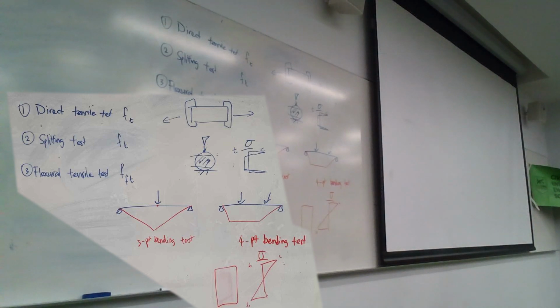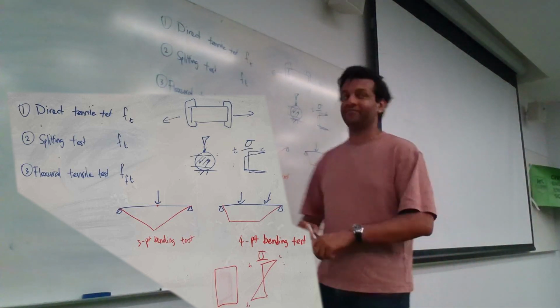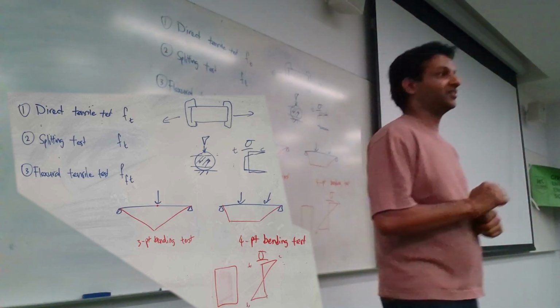Yeah. Mike, can you test it with the UDL? What's the problem with testing with the UDL? Testing with the UDL is not the same thing as testing under one point load, but you're not evenly spreading out the bending moment, right? Because what does a bending moment diagram for a simply supported beam with a UDL look like? Okay. You sure? Okay. Any other questions?